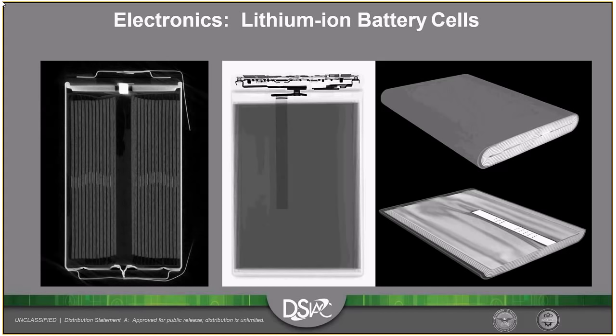And we've gone into this a few times. One of the best examples is a rocket motor that experiences charring, and trying to get that virgin material and that char line. That's all subjective. When do you want to define that threshold? It's really up to the user. So having different density standards that say this is a charred material, this is a virgin material, you can then define that number, that ISO value, and program that directly into the software. It would take a lot of effort up front to make sure you have all of that information, and then you can automate that and post-process on the backside.